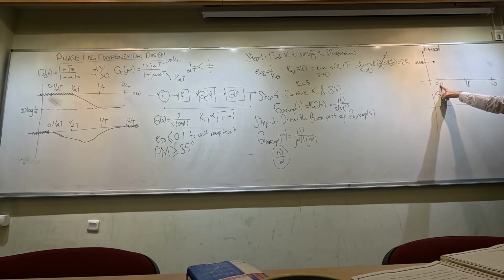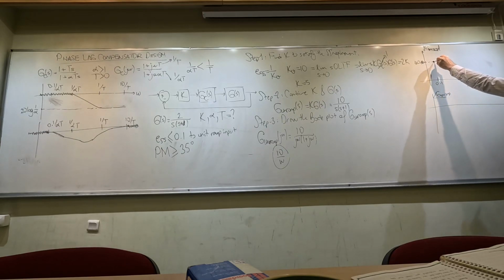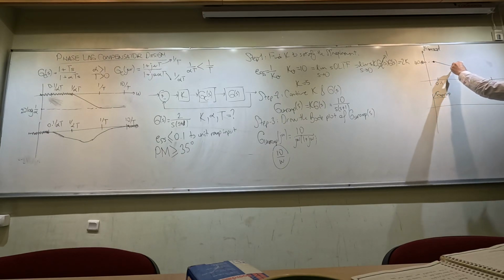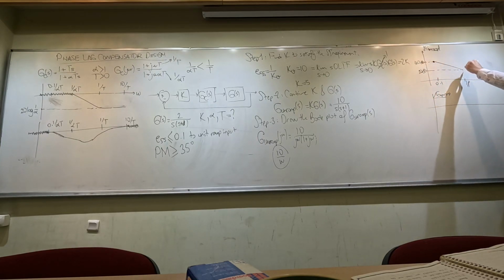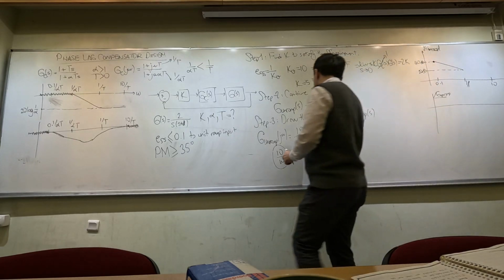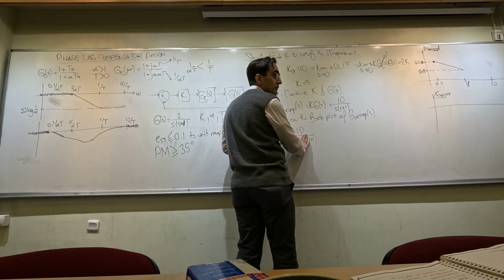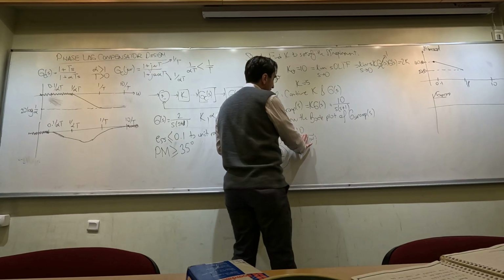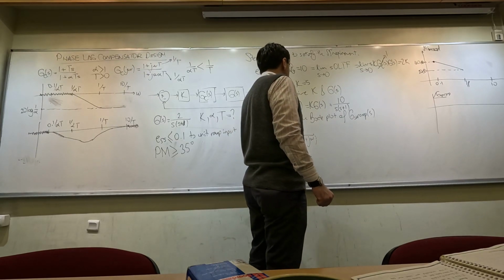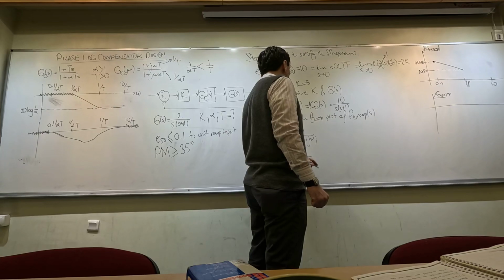So the frequency increases 10 times from 0.1 to 1, meaning that the magnitude is going to decrease by 20 dB here, and it's going to come to 20 dB at the frequency 1. Okay? And when we pass the corner frequency 1, then I'm going to start neglecting this 1 here. Okay? If frequency is above 1, then I'm going to neglect this 1. And then the magnitude is going to be looking like 10 over omega squared.